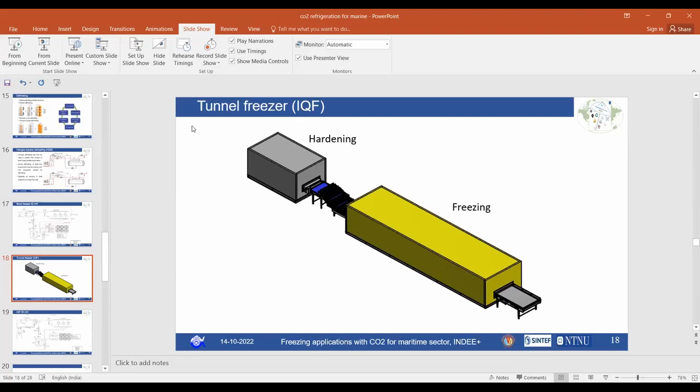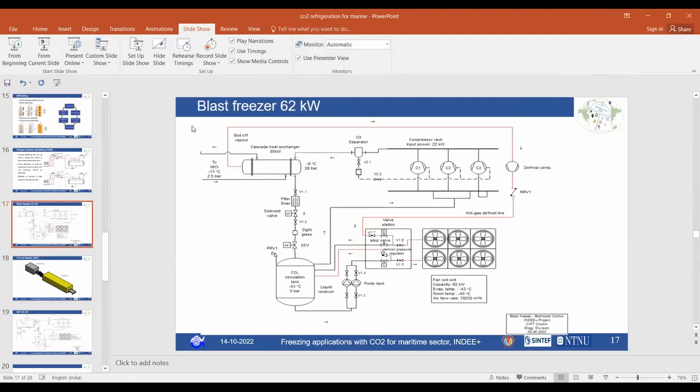Yes. Dr. Arun, Lakshman here. I had one question on defrosting. Instead of having a separate CO2 compressor for defrost, why don't you have a brine glycol solution pump through the system? Yes, sir. That will also be an excellent idea. If you need to cut the cost, you can have a glycol pump also. In fact, the heat can come from the ammonia system with a plate type heat exchanger. Yes, sir. That's a good idea.